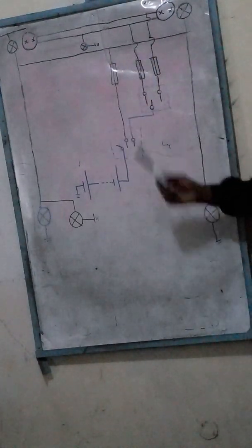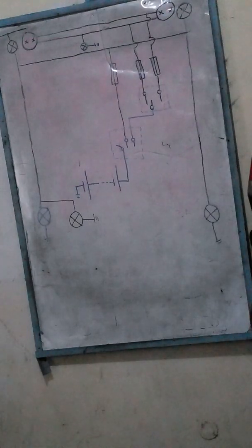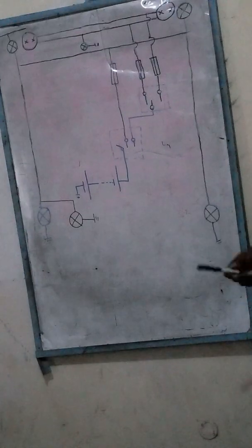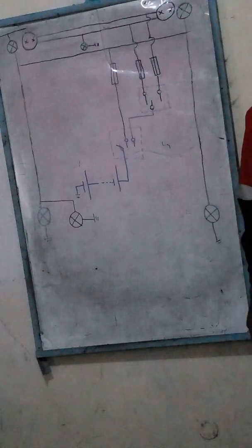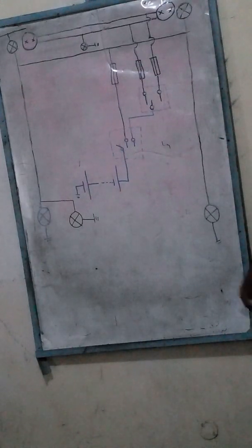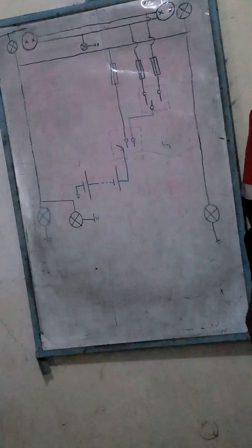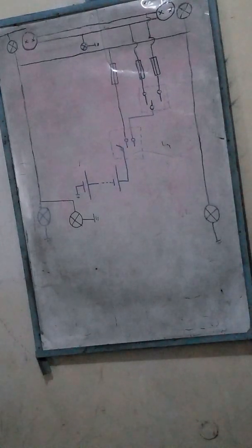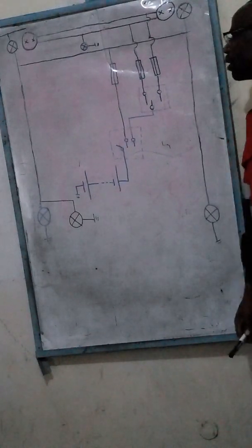Both filaments, left and right, may have been affected by a short circuit and blown. And in some cases, overcharging of the alternator may cause, especially the high beam filaments, to blow. So it could be a case of high charging rates. Check your charging system if you suspect it is failing.